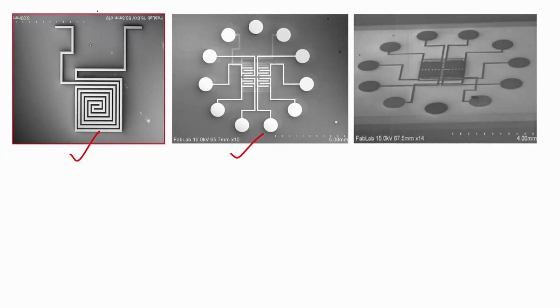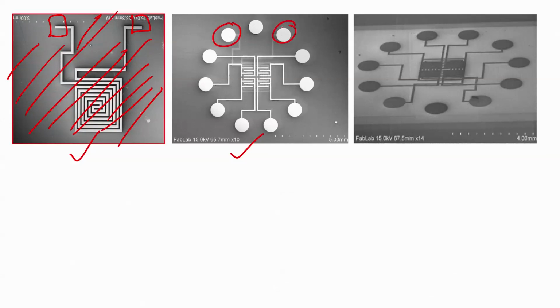Over this there is an insulator, on which there are these interdigitated electrodes. And then we also saw that we have to create a window to open this area and remove the insulator from that area, so that we can have an external contact. You can see here contact pads for the micro heater.